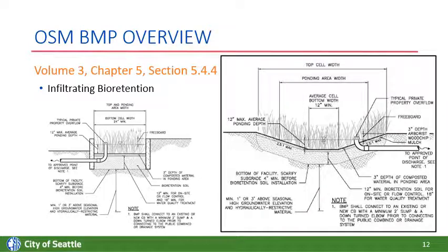So there are situations where you may be placing a bioretention underneath a walkway or underneath a roof overhang. And if the licensed architect says that, for one, that's the only location that you can site this facility, and also that the specifics of the site are such that the required plants will not be able to survive in that level of sunlight, then they can be replaced with wash gravel or mulch.